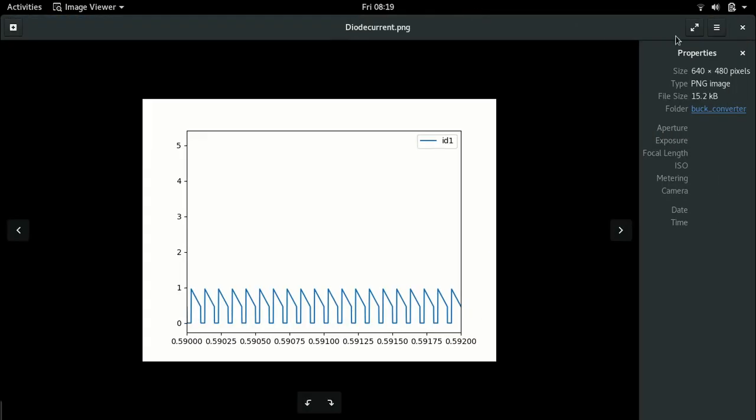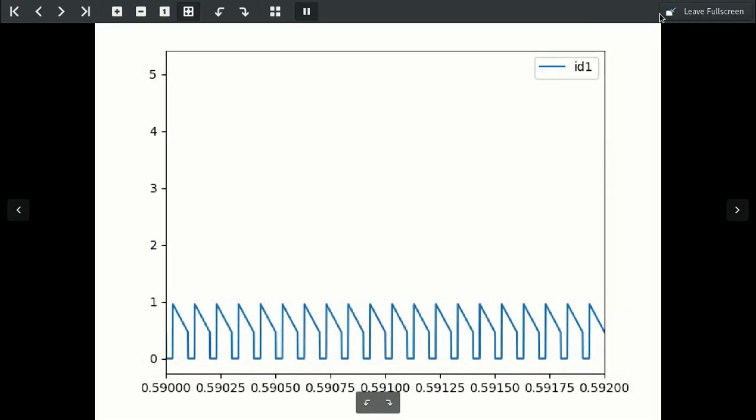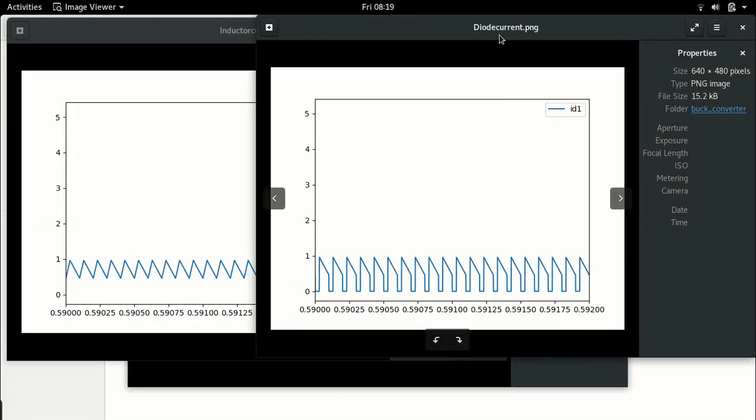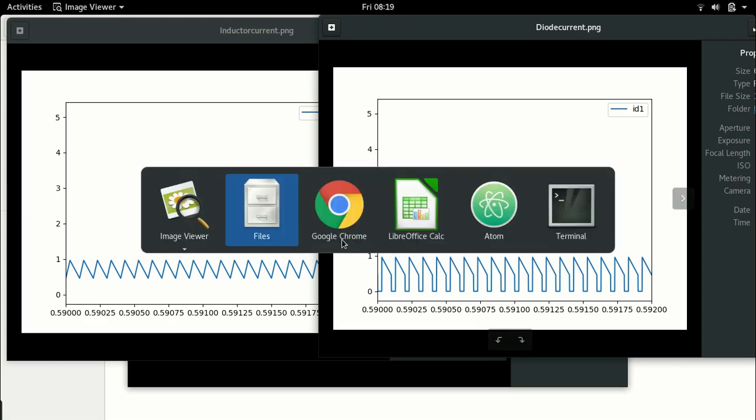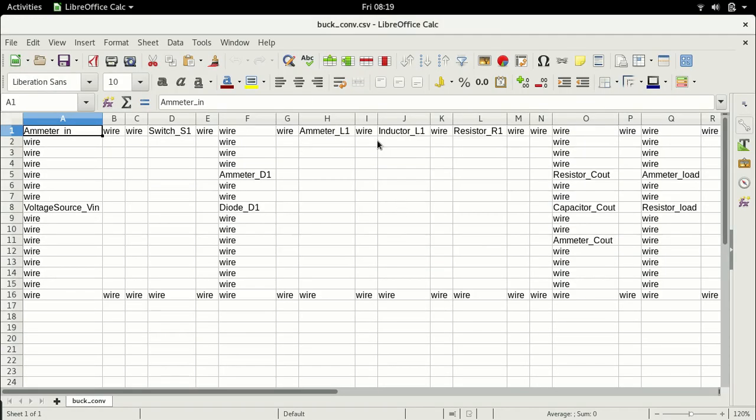Now, I didn't want to expand on this. So the main thing about this is, the inductor current is the current through this inductor. Right? And the current through this inductor is flowing in two stages, right? There are two states in which it flows. There's one part where it flows through the switch and the other part where it flows through the diode, right? So it will be interesting to compare the diode current, the switch current with the inductor current.